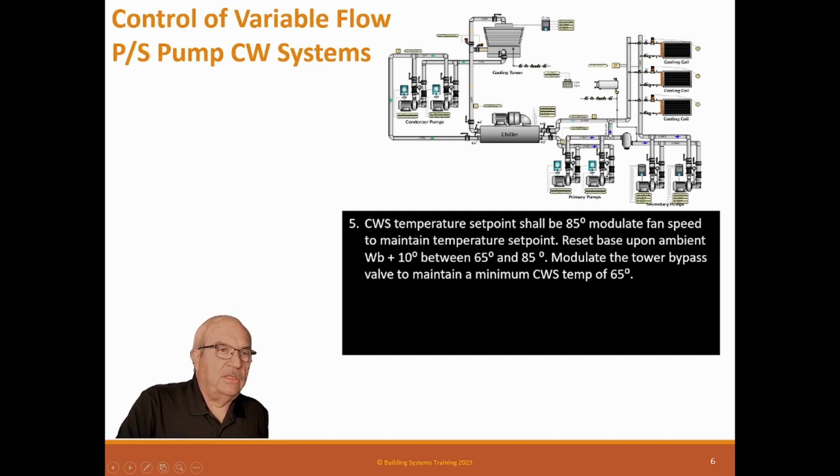So the chiller has to actually take and cool the water, but the higher the water temperature entering the chiller, then the higher the lift it has to make in its temperature. So if you can get this water colder entering the chiller, then you're going to have lower lift. But there is a limit. Chillers can't take infinite cold water, right? So normally it's about 70 degrees. Some of them are 65 degrees. It depends on the manufacturer. But what we want to do is drive this water down as cold as the chiller will take, so it'll be as efficient as possible.